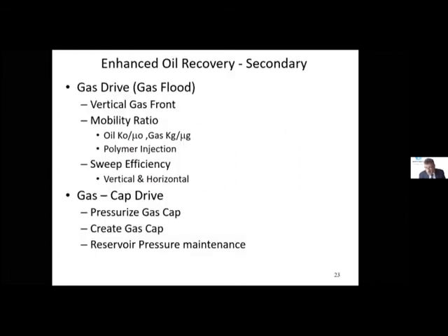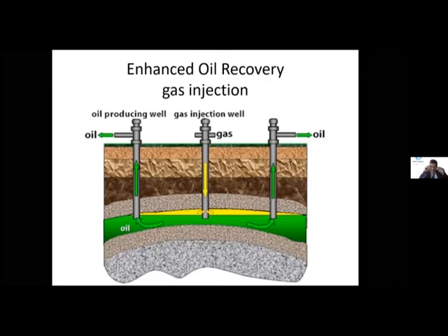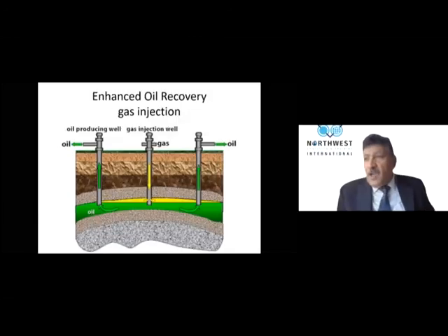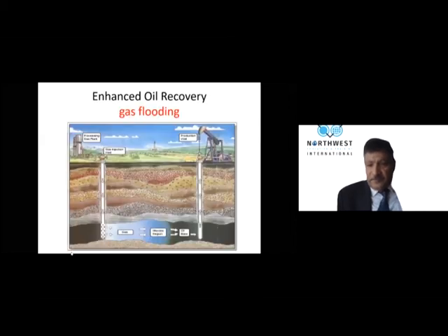So if somebody asks you, we have no gas cap, can we use gas injection? The answer, no. We use the gas flooding in this case, which is similar to this slide. The gas here is targeting the oil zone. I will call it gas flooding.